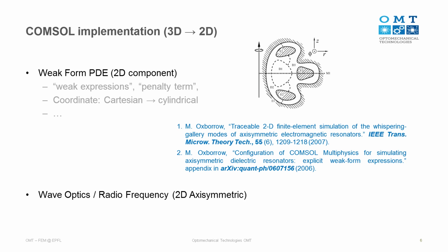So let's go back to the implementation of looking for modes. Apparently, if you want to do investigations on microresonators, the first step is to know what the resonance is. I mean, what's the frequency of the resonances and how the mode looks like. So in COMSOL, we can implement it and find such an eigenmode.